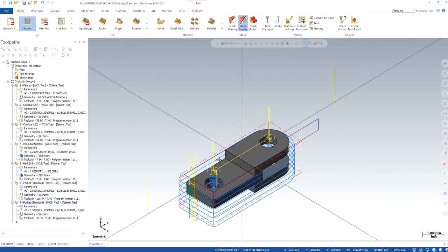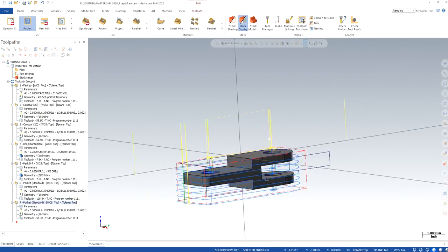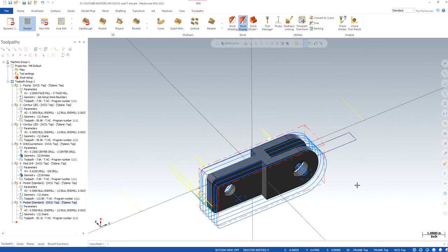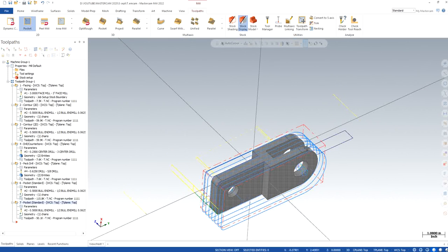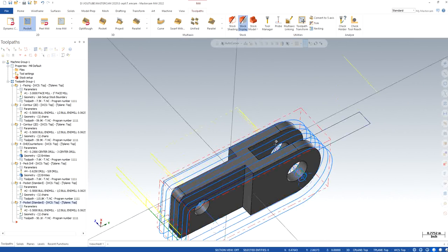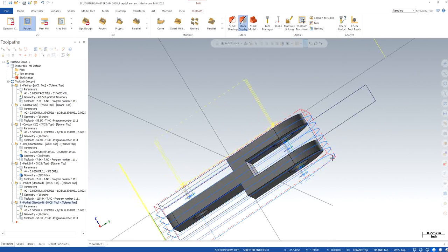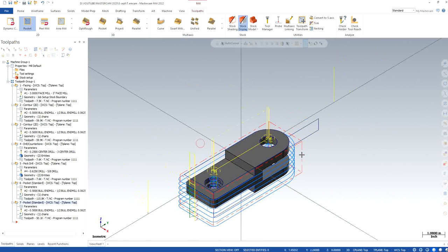We can, if we want to, just chop off this extra material, we can have roughing operations, we can set up another plane in this way and make a tool pass in such a way that we get rid of this extra material right there, but we need to make sure that there are sharp corners in this part. Cutting with any CNC tool is going to be giving a radius, so it all depends on if those kind of specifications work, then that's not an issue. If they don't, then EDM is the only way to go.